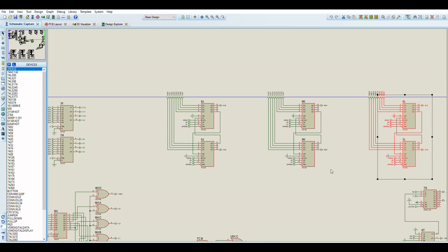Or horizontally flipped, sorry. So if you are not horizontally flipping the sprite, then all it does is read in the 1 byte, 8 pixel values here, and then it shifts it out one way, for example. But if you are horizontally flipping the sprite, all you need to do, basically, is shift the other way, which is what these lines do here.